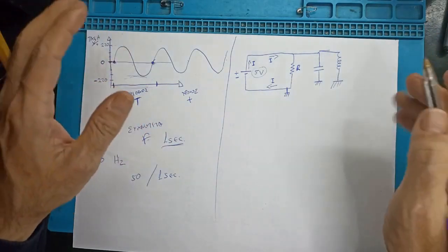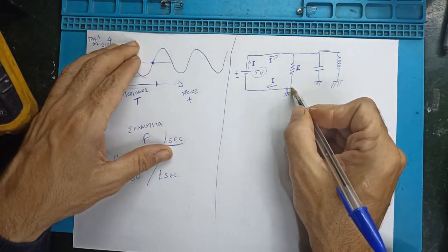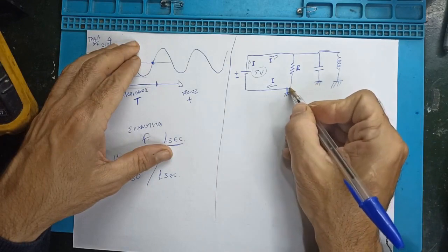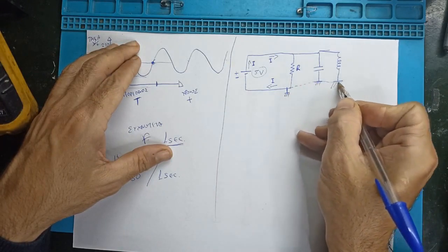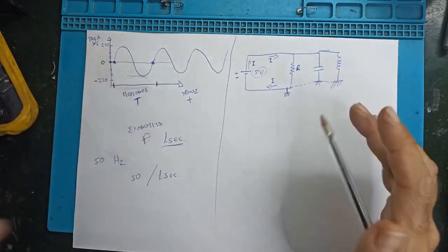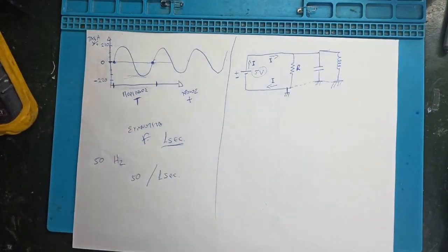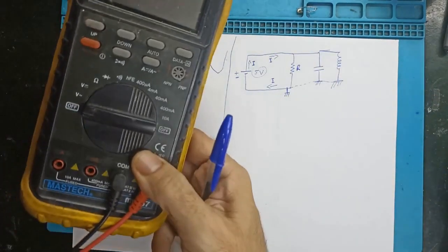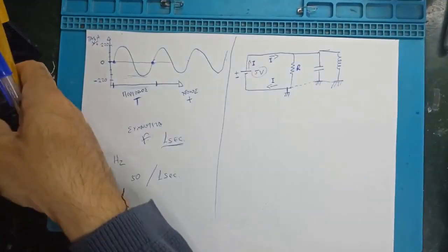This is understood in the plans when we read them, and there we usually also put the probe of our multimeter, or the grounding of the oscilloscope, and we start taking measurements with the positive or with the negative in the rest of the circuit to find some fault.